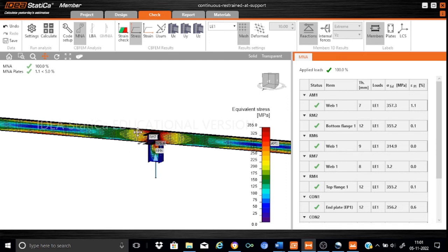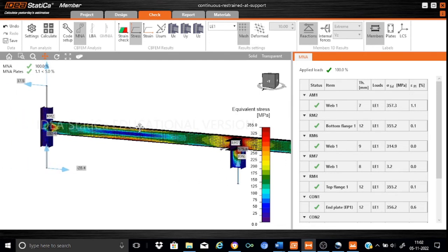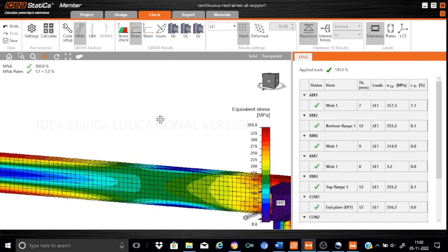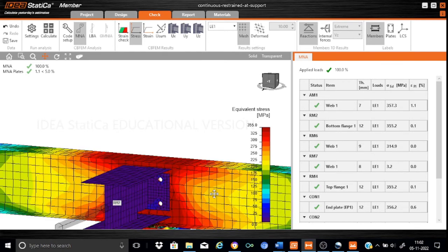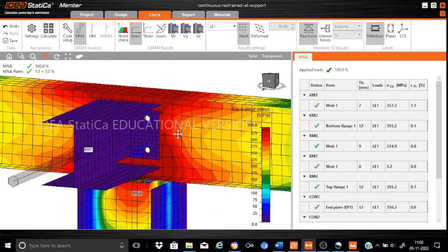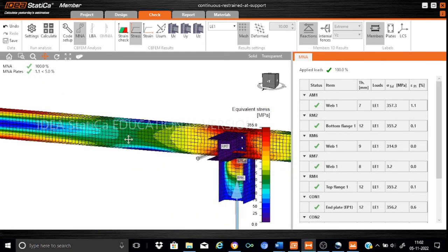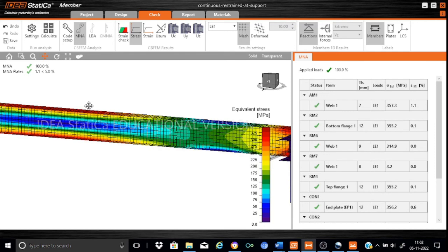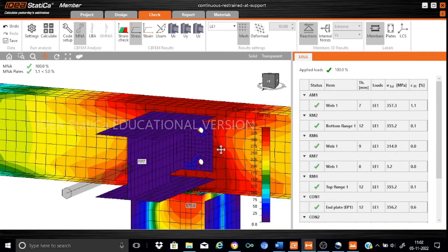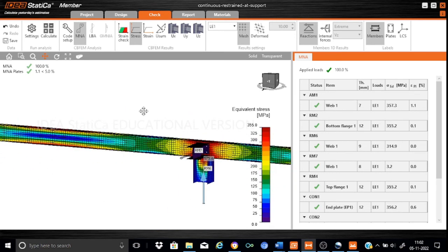So look here, this is what we have expected. Our stresses are not that critical. This section is almost at the 355 level, right? The midspan section is almost critical, and the support section is almost critical. In the stress distribution at the midspan, the stress is rather concentrated near the flanges because of the lesser moment. It does not drop down to the web portion, and here you'll find that the entire section is almost on the verge of plasticization. So this is regarding the stress distribution.